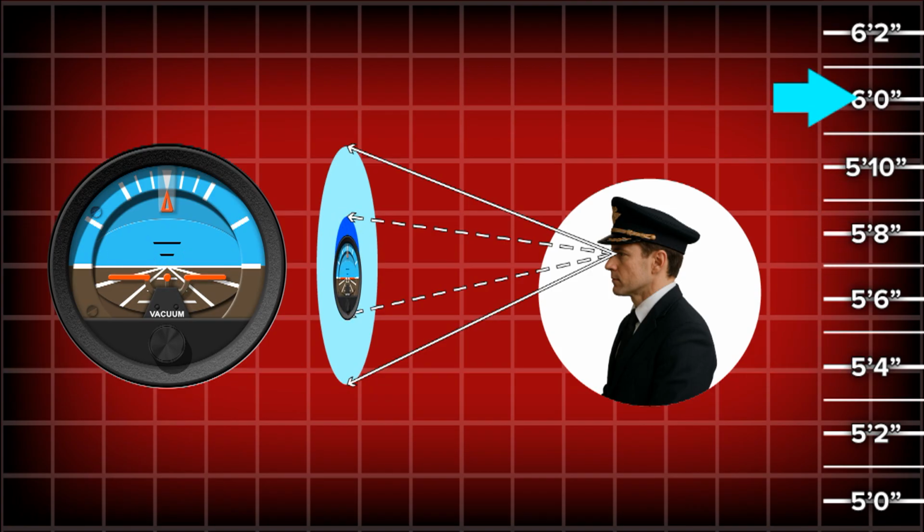So when entering the cockpit, a taller person may have to adjust the knob to increase the height of the miniature aircraft, so from his or her point of view, the miniature aircraft now appears level to the artificial horizon line, whereas a shorter person may have to adjust the knob to lower the miniature aircraft so that it now aligns with the artificial horizon line.